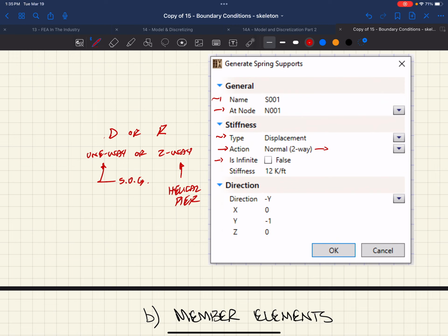With respect to displacement or rotation, well, we talked about rotation, right? Sometimes we would want to do rotation for maybe a side plate moment connection, right? I talked about proprietary moment connections like the one from Nucor, our side plate. We give our model to side plate. They manipulate it, size the members, beams and columns specifically for our moment frames, and then they input into our model the stiffness of that intersection, which with side plate got way stiffer than it would be with just the two values of our column and beam, because we put these huge plates on the sides of our elements. And so we ended up with a big difference in stiffness, and so they needed to adjust that, right?